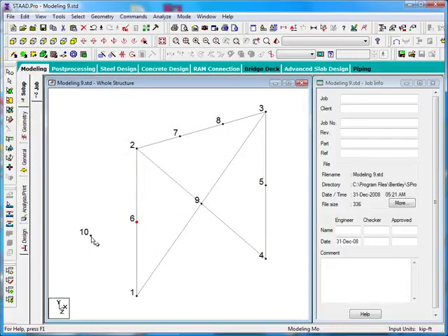And now I can see the new node, which is node number 10, and it occurs out here to the left of node number 6. Now it doesn't actually have anything to do with copying and pasting nodes, but what I'll do to set us up for our next step is just come back to the Add Beams tool, and then I'll add a beam from node number 6 to the new node number 10 so that we actually have that 2.5 foot long cantilever, beam number 12, with a length of 2.5 feet.